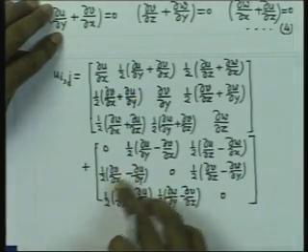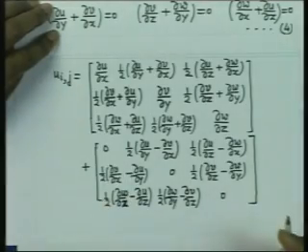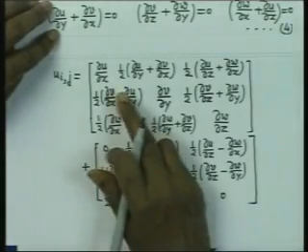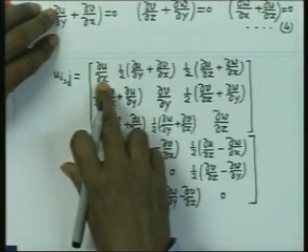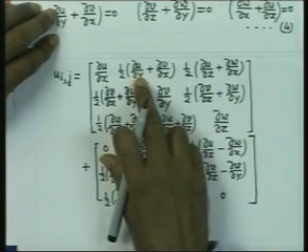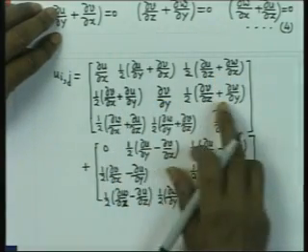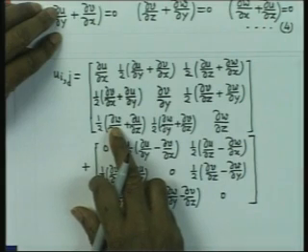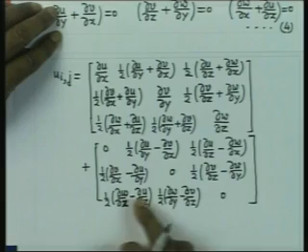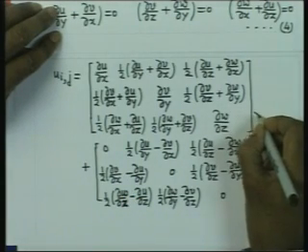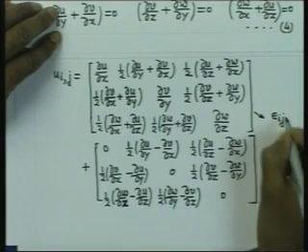So, if we just write this, we get back, you can see that here we have added something, we have subtracted something, and then these two terms give me back the original expression for Uij. You can see that this is nothing but the strain tensor. This is epsilon x, gamma xy, gamma xz, gamma yx, epsilon y, gamma yz, gamma zx, zy, and epsilon z, and this is the strain tensor epsilon ij.